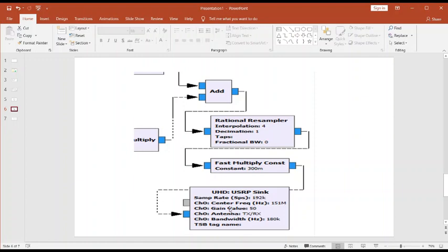So here you can see we're telling this hardware sample rate 192 kilohertz. We're telling it a carrier frequency of 151 megahertz. I put the gain up to 50. That seemed to be pretty strong. It was around 0 dBm. So, obviously it's not going to have much juice. You're going to need some power amplifier, but for me, just to test it within my property here, 0 dBm was plenty of power. And I set the bandwidth to 180 kilohertz.